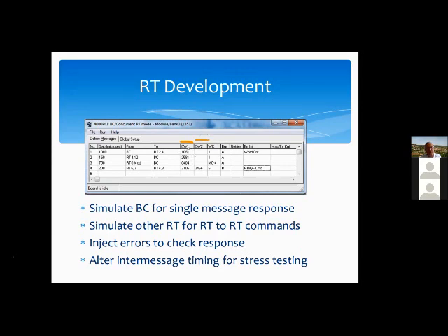It turns out that a 1081 is a BC to RT command because the 6th bit from the left is a 0, so the TR bit is a 0. It's got a single data word, the 1 is the low thing, and it's RT to subaddress 4, which you'll have to take my word for. So here you've got all the messages that we want to send: BC to RT, an RT to BC, a mode command, and an RT to RT. These are the 4 basic types of messages.